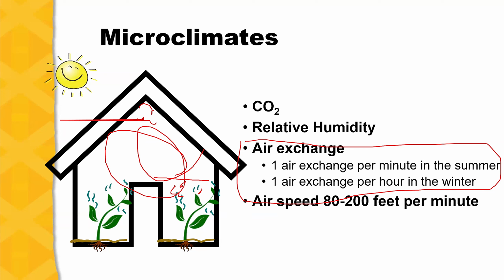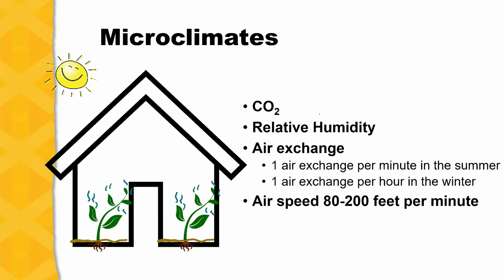During the nighttime, when there's no light, plants are a fascinating organism. So during the nighttime, when there's no sunlight, some plants will go on respiration. And what that does is that the plants are going to use oxygen and generate CO2. So during the nighttime, you also want to have air exchange, right? When the plants are respirating, they're also transpiring, right? There's also some water coming out. So you also want to have some air exchange, but not so much during the nighttime as opposed to the daytime.